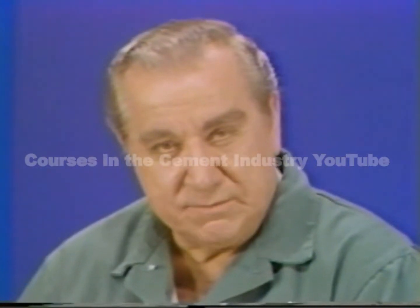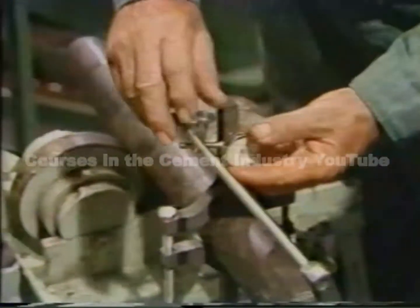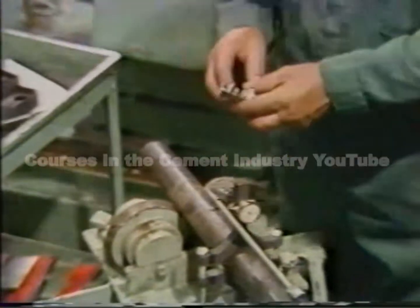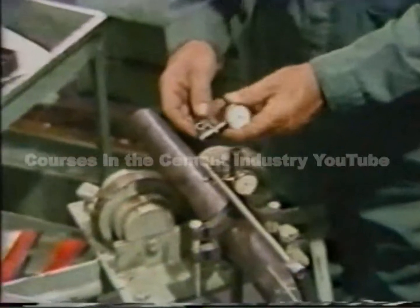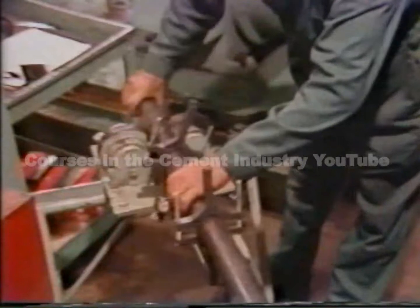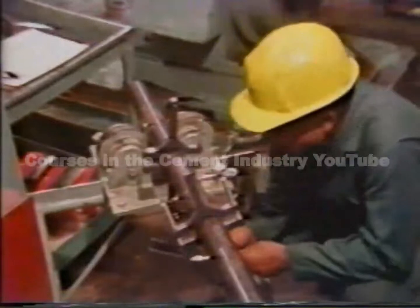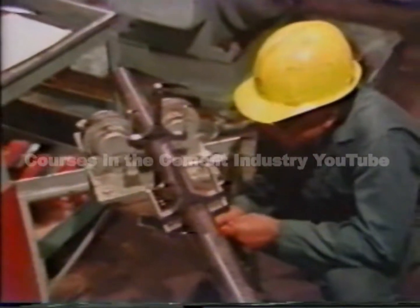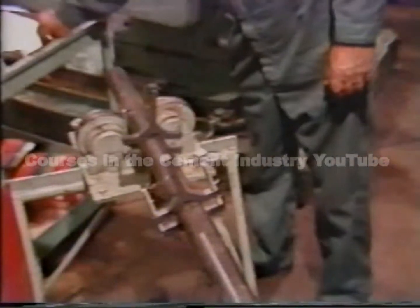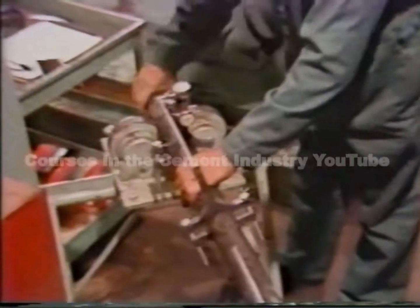Let's review now. Before the dials are installed on the shafts, they should be installed on a pipe or other rigid material to determine how much sag exists. Bracket sag only affects the bottom parallel alignment reading. So sag will be accounted for on that reading during the alignment job. Stop now and review dial indicator mountings and sag with your instructor.